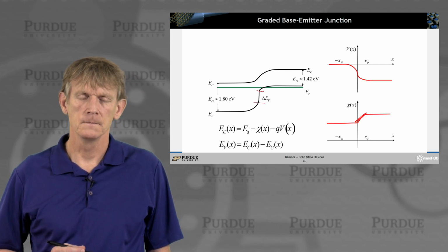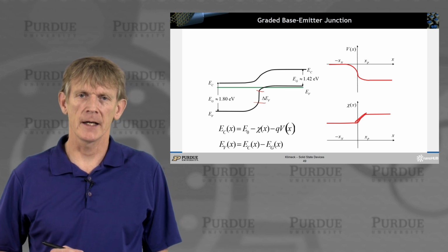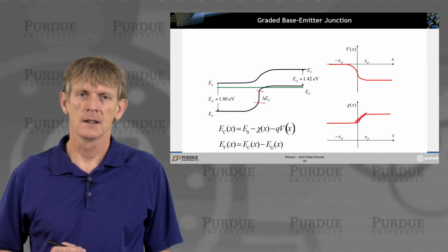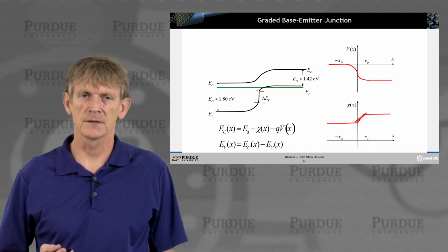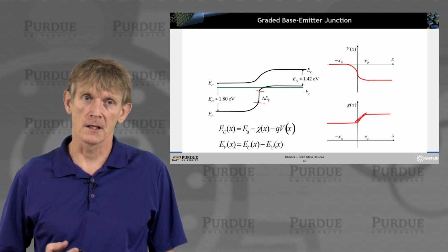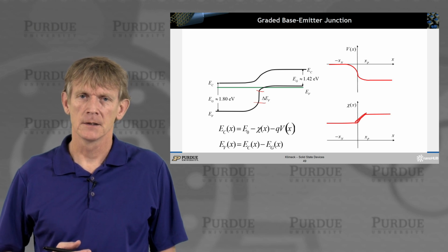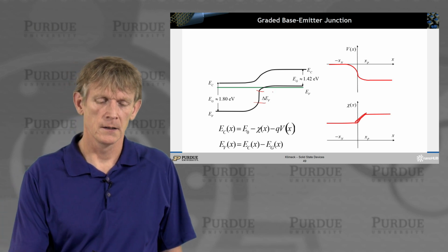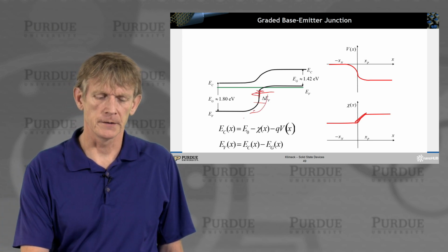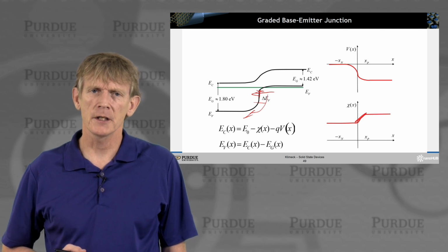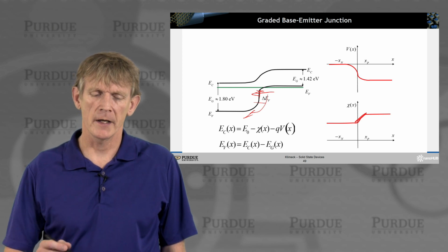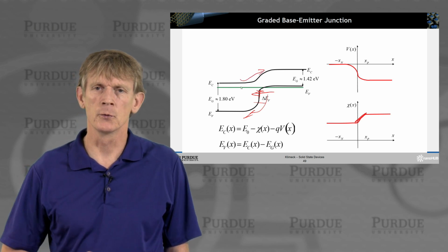And basically you've increased here the difference of the band gap quite a bit here in the valence band. So you transitioned the difference in the band gap into a region where you don't care, or you actually like it to be, right, bigger. Because what you really want is you want to block holes flowing in this way, or more accurately, this way, right? So you increase the gap in the right direction where you want to block carrier flow, and you make the transition for electrons smoother.